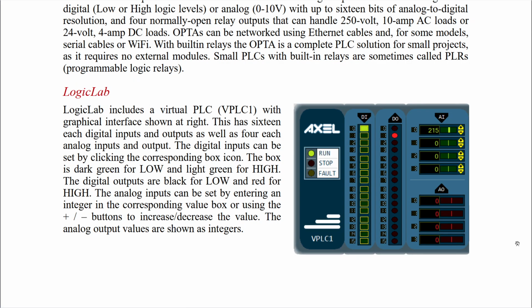For simulation, we're going to use the freely available program Logic Lab. It has a virtual PLC called VPLC1 built into it. This is the interface. It represents the digital inputs, digital outputs, analog inputs, and analog outputs for this virtual PLC. A nice thing about it, it has virtually the identical interface as the Arduino PLC programming environment. And therefore, we can use this on our individual PCs and simulate the PLC operation, and then that exact same program can then just be run on the Arduino.